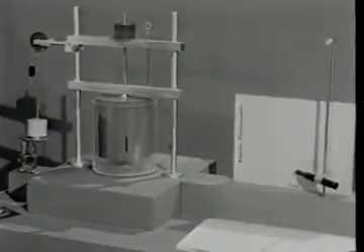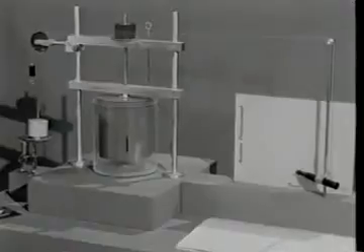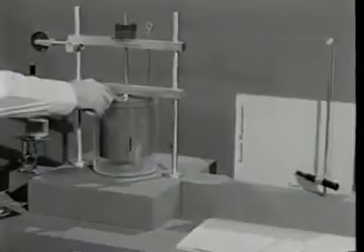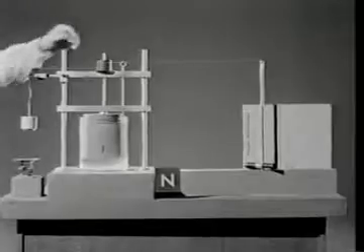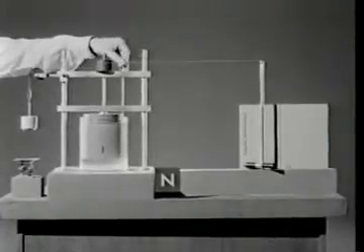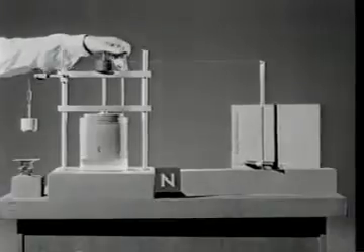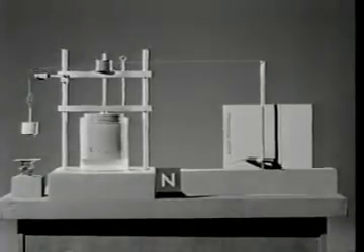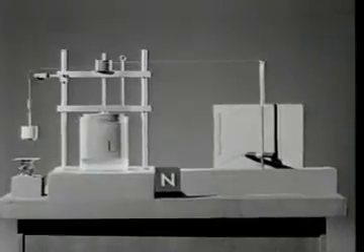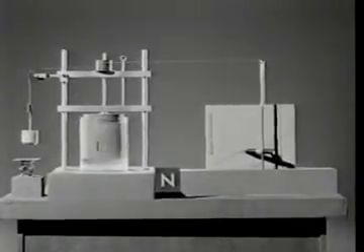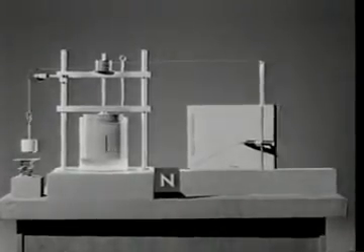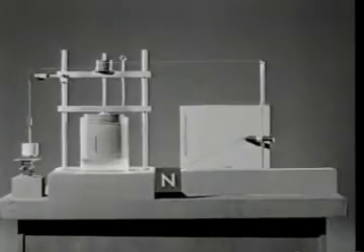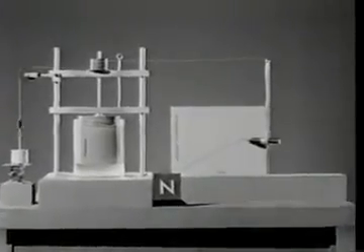We have, of course, designed this experiment to minimize extraneous effects arising from the inertia of the fluid, the inertia of the moving parts, and from friction. The first experiment is with a Newtonian fluid designated by the letter N. A constant velocity is attained almost at once since inertial effects are small. Now the applied torque is zero again, and the cylinder stops immediately.